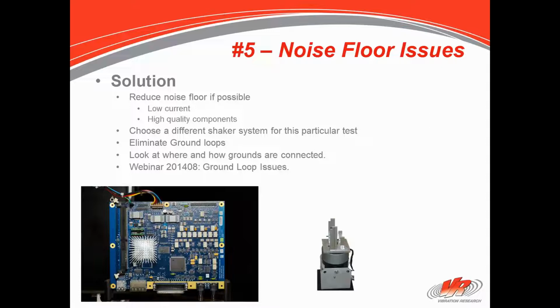If you want to get rid of all of that noise, the best thing to do is power them from the same raw power source. That might mean finding a tap inside your amplifier console to power the controller from. That may eliminate much of the problem right there.